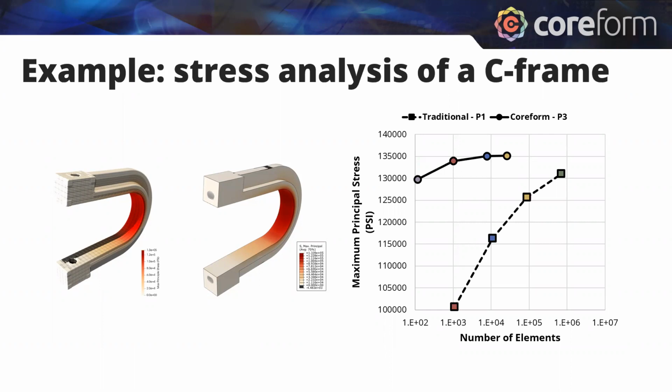Yeah, that's a very insightful question. How would one go about quantifying the numerical uncertainty due to convergence within IGA? So I'm not exactly sure what's being asked there. One way is, if you have condition numbers, the order of your condition number tells you in some sense how many decimal places, starting at the least significant, so all the way down, so 1.00001, it tells you how many of those digits you can't really trust in your final solution.